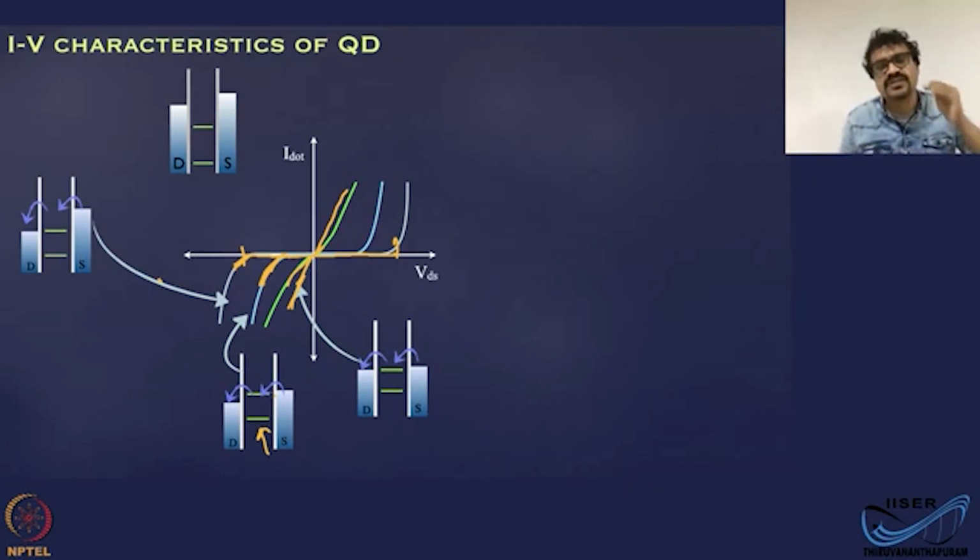It's an induced charge from the gate. There are two ways to do that. So when you apply a large source-drain bias, the current will turn on eventually. But if you push the levels into the window by a gate voltage, then you can turn on the device even at a much lower voltage.